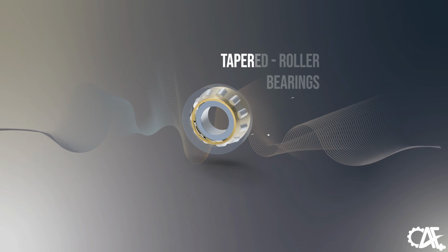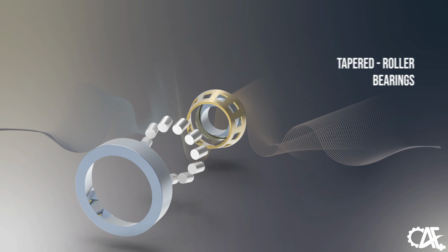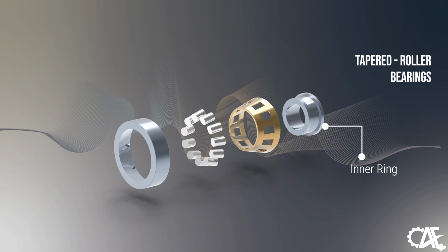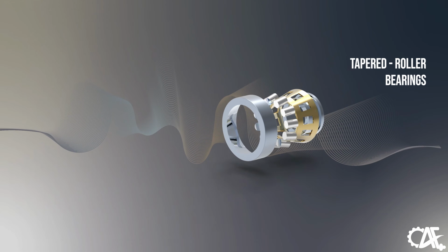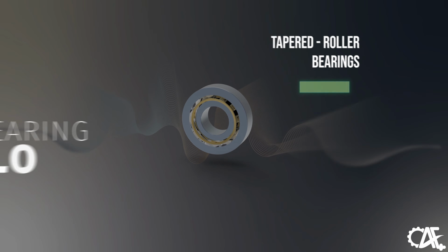Tapered roller bearings consist of tapered rollers, a cage, and two tapered inner and outer races. Tapered roller bearings are designed so the inner-outer ring raceway and apex of the tapered rollers intersect at one point on the bearing center line. Their tapered design enables them to support both radial and axial loads effectively. Moreover, they provide smooth and efficient load distribution, reducing the risk of edge stresses and increasing the bearing's longevity and reliability.